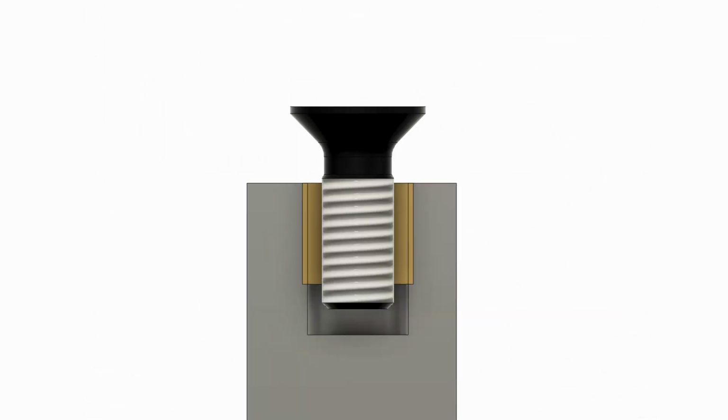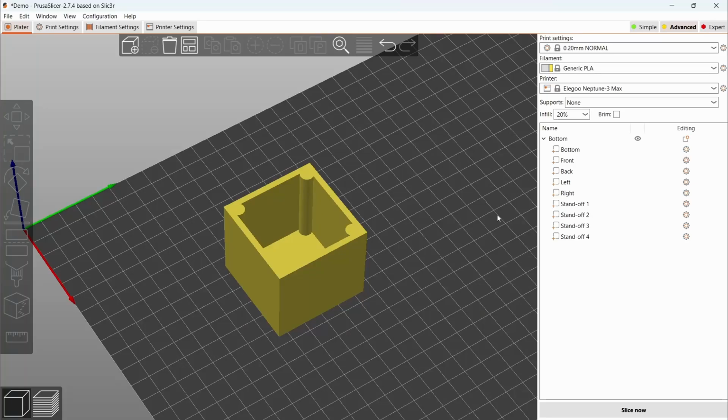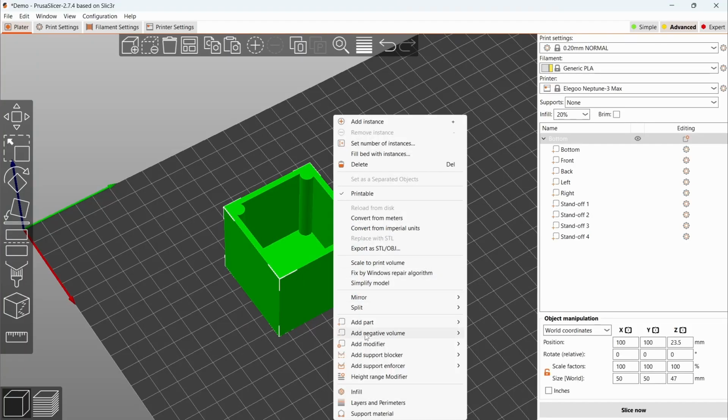The length of the hole is also important, since there needs to be enough room for both the insert and any portion of the screw that extends past the end. Let's design for 8 millimeter screws, and since the lid is 3 millimeters thick, our hole should be about 6 millimeters deep. That allows for the screw to extend up to 2 millimeters past the end of our 4 millimeter long threaded inserts. Let's start by creating a negative cylinder